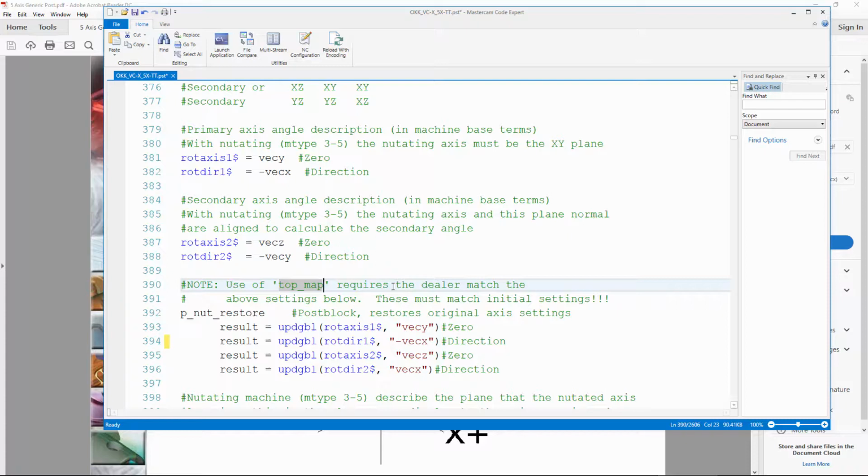And this has quite a bit of advantages, especially on a machine like a Gantry. So normally on a Gantry style machine, we can only use canned cycles if they are aligned to a plane. So if they're aligned to the top plane, which would be G17, then we can do all our normal drill cycles. If they're aligned to one of the other planes, we're either going to be in G18 or G19, and we can still do all of those drill cycles. We can also use cutter comp.